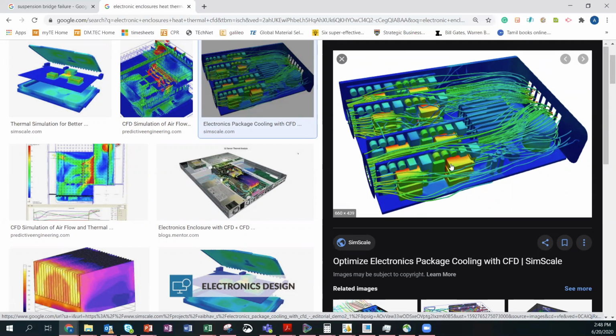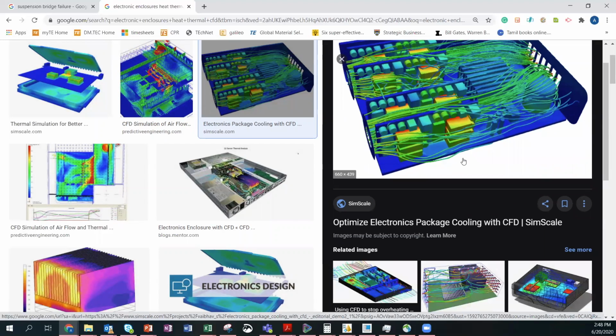So what happens is, you see all these red lines over here? Yeah. So these are all to the PCB. You have all the capacitors, insulation, processors, and everything. They get heated up. Right now in your computer, as we speak, it's getting heated up. So there is a life. Any laptop you buy, you want it to last at least 4 to 5 years, right? Yeah. So the life is directly proportional to the temperature inside the enclosure.